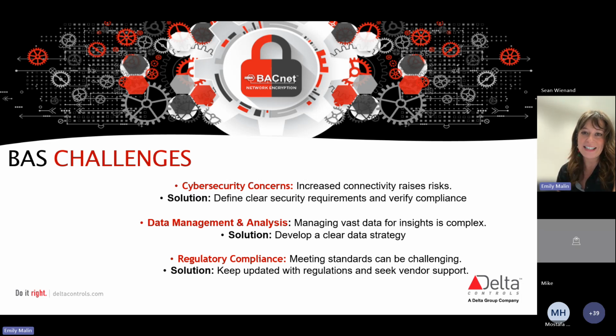Data management and analysis is another challenge. We had this obviously in our benefits as well, because it's a benefit and a challenge. Once you start getting all of this data poured in from all of these different sensors, now it's like, well, what are we going to do with it? We have all of this data coming from every different zone in our building. We're measuring humidity, temperature, indoor air quality, CO2. We have all of these things, but what do we want to do with it? That's something that you definitely need to be thinking about on the forward front instead of on the back half: what's your plan? How do you want this data to be presented, and what do you want to actually do with this data?